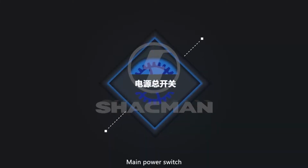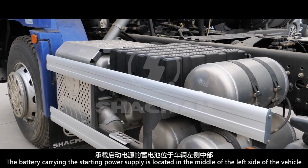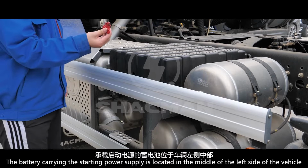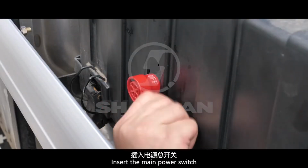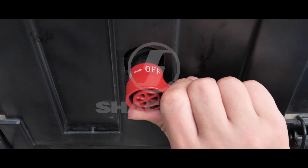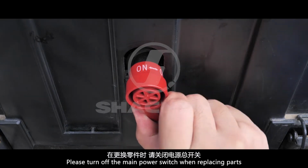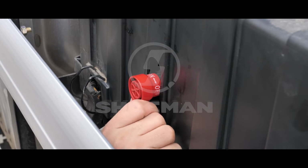Main power switch. The battery carrying the starting power supply is located in the middle of the left side of the vehicle. Insert the main power switch. Turn to on and turn on the circuit. Please turn off the main power switch when replacing parts.